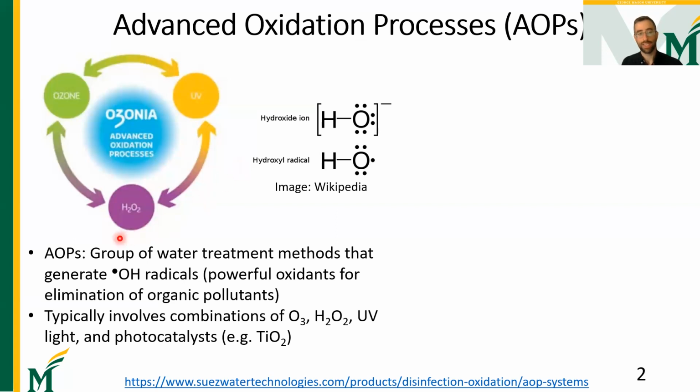Advanced oxidation processes are broadly a group of water treatment technologies that rely on the production of powerful oxidizing species, most notably hydroxyl radicals, to degrade a wide range of organic pollutants in water. AOPs typically involve a combination of ozone, hydrogen peroxide, ultraviolet light treatment, as well as photocatalysts.